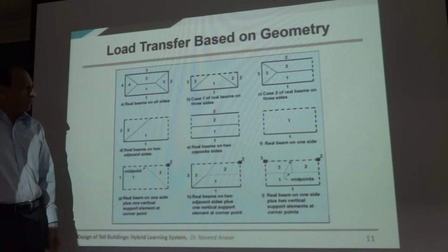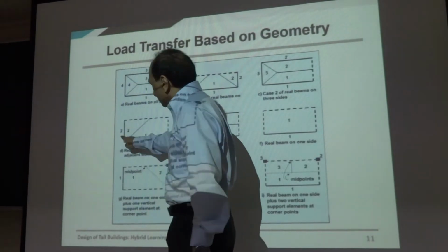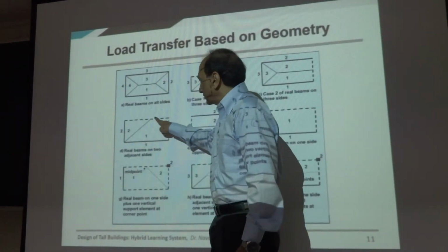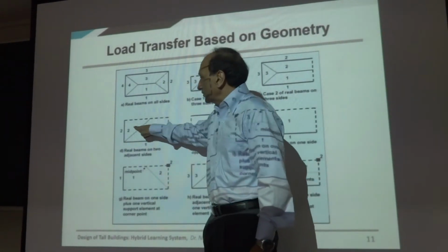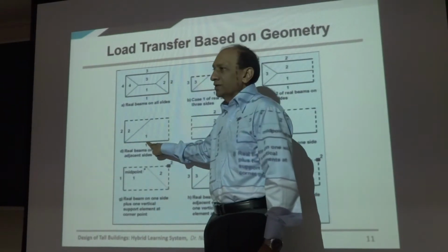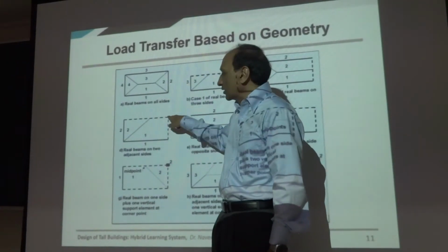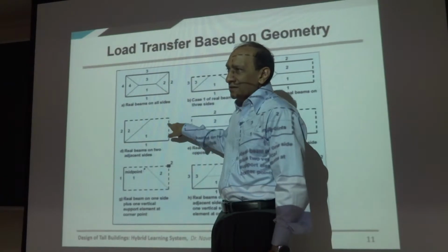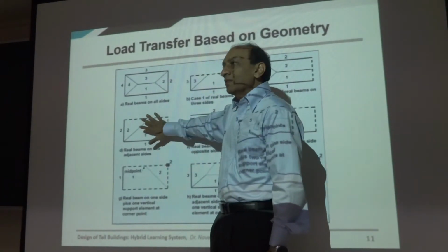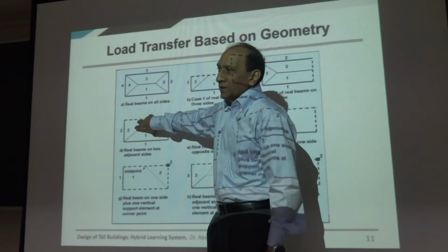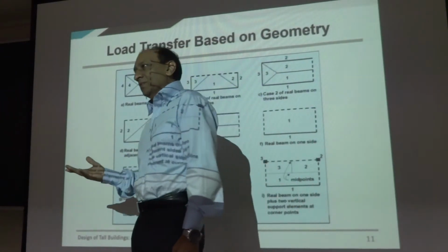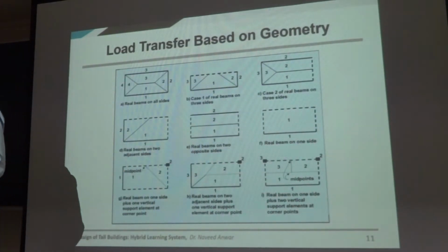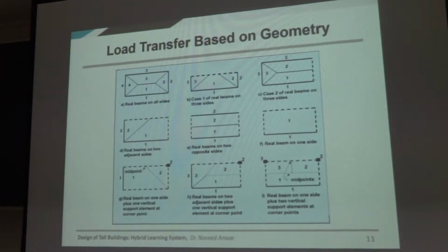Conceptually, for example, if you had only two walls and no walls here, then load will go here, this load will go here. Of course, this is not a stable structure. This corner will go down, right? It's a cantilever. But suppose you somehow managed it, load will go this way. It doesn't mean that the structure is stable. It just means where the load will go to the supporting system. Not talking about the design of the slab itself, rather the load transfer.